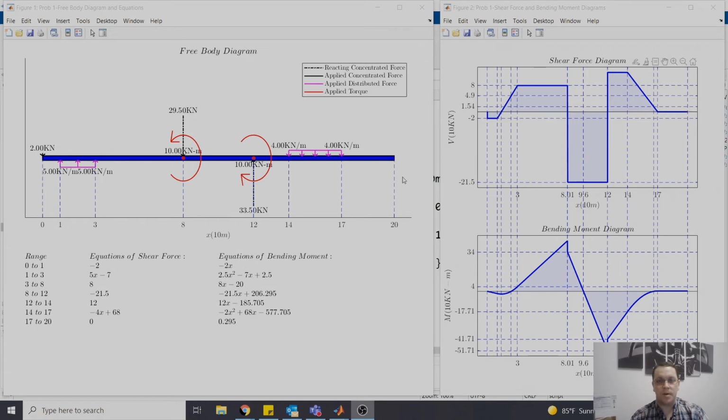Back down here at the end, you want to think about, well, this is now 0 for the shear at the very end. Well, why is that? Why is it 0 shear out here at the end? So these values, by comparison, have to be much, much stronger supports in order to be inboard. So you want to keep that in mind as you're going through each of these steps and explaining what's happening with the diagram, how it changes so drastically between the two supports as far as the total bending moments. One's going one way, one's going the other way.